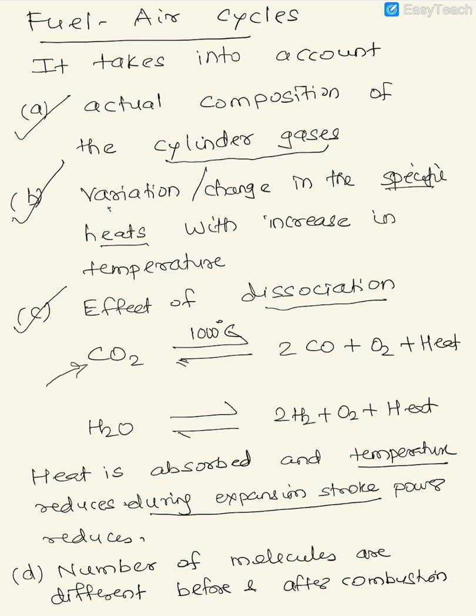Like the CO2 would dissociate to carbon monoxide and oxygen, the water vapor would dissociate back to hydrogen and oxygen. When this dissociation happens, it is an endothermic reaction and energy is absorbed, and when the energy is absorbed, the power which is available during the expansion stroke, as predicted in the air standard cycle analysis, is reduced. So this is the effect of dissociation which the fuel air cycle analysis does consider, and which is neglected in the air standard analysis.